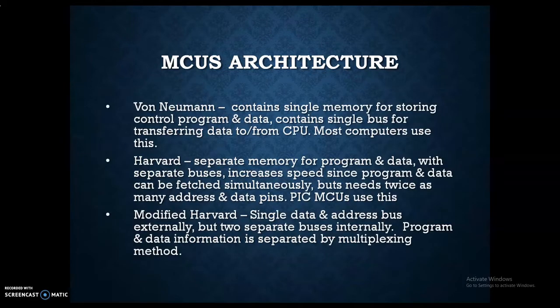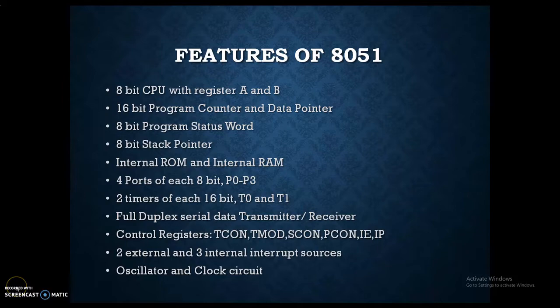So coming back to the gist of this, modified Harvard is also there. A single data and address bus externally, but two separate buses internally. Program and data information is separated by the multiplexing method. So it is the advanced version of this Harvard architecture.